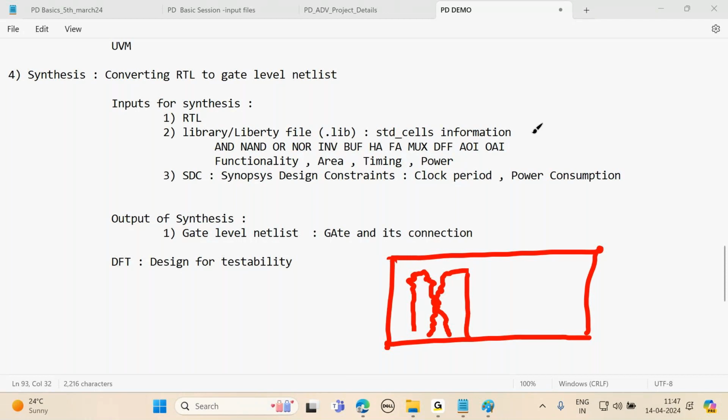Actually, I want two separate metal layers, but internally they are shorted, because during etching the foundry has not etched properly. It is a chemical driven process. They do not grind with a grinding machine. The chemical has to etch it, or acid has to remove it. Here acid has not removed it, so now there is a short. This short will never allow my IC to work properly.